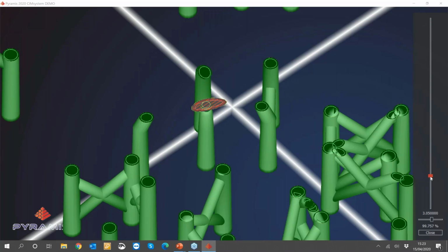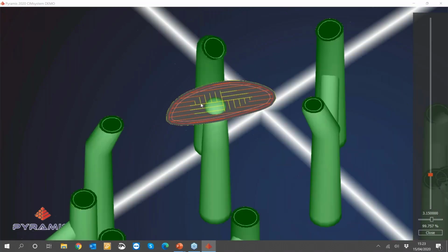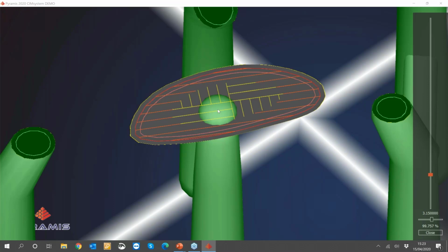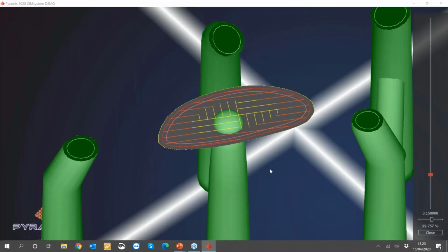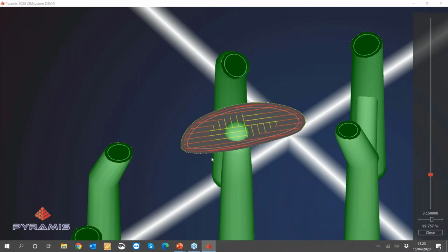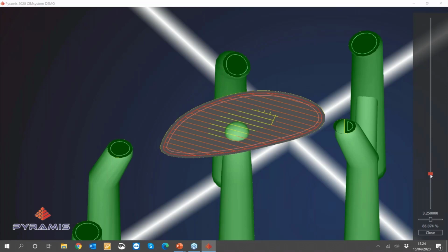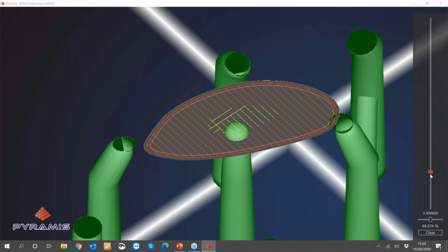As you can see, there are different colors for each laser path because we can define different areas for every layer. For example, for external areas, we consider them bottom layers, bottom skin or up skin. So depending on the part of the object, we can make an analysis of the object, a kind of intersection between layers, to define a part of the object that we want to consider bottom skin or up skin, in order to assign to this specific path different parameters, for example, different power or different speed, in order to obtain, for example, different surface finishing. So you can see here that every single layer has a different definition of the areas.